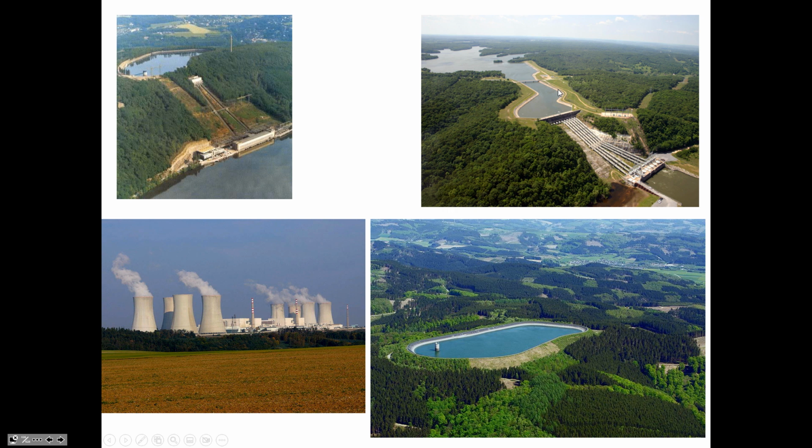And so what we're talking about with pumped storage, I guess in a sense, is arbitrage because you're buying something at one time of the day and you're selling it at a different time of day. And the thing that you're selling is the exact same product as what you bought. You bought electricity and you're selling electricity. And the interesting thing in the case of pumped storage is you're actually selling less electricity than you initially purchased. But the reason why it's profitable is the time of day that you're selling the electricity, there's more demand. So in the case of pumped storage, what they do is they buy electricity at night and then they sell it during the day.